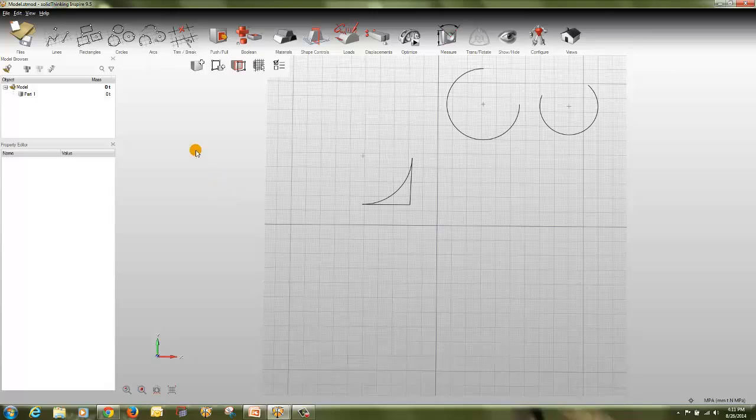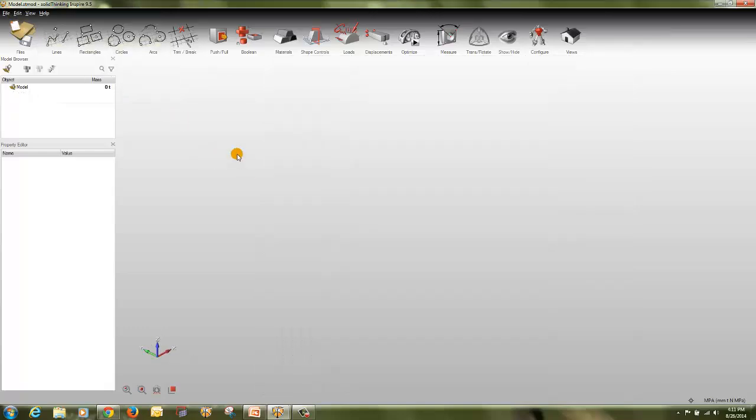So now let's talk about some sketch constraints. I'll have the new file. So we'll see about the sketch constraints. When sketching, you can apply geometric relationships such as tangency, perpendicularity, etc. to lines, rectangles, circles and arcs using the sketch constraints. As you sketch, Inspire automatically applies many constraints for you. For instance, if you draw a line that is nearly horizontal, a horizontal constraint will be created on that line automatically, making it precisely horizontal for you. When you modify a sketch, the constraints ensure that the intended relationship between the sketch entities remains intact.